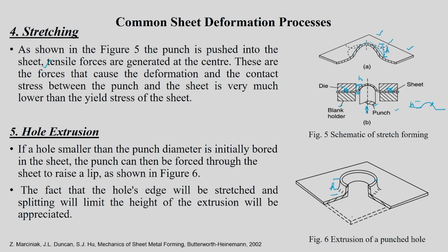Okay, lip. So now what will happen? This whole edge will undergo a typical deformation process, and the material should not fail before it reaches one particular height, and especially failure will happen mainly in the edges. So you have to be a little bit careful in that. So hole stretching, or extrusion of punched hole, is very important to understand how the hole is going to deform when you go for the actual sheet forming process.